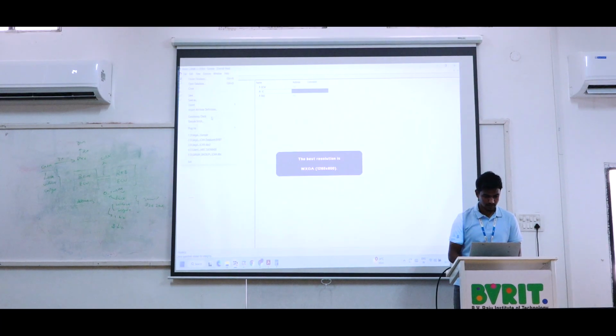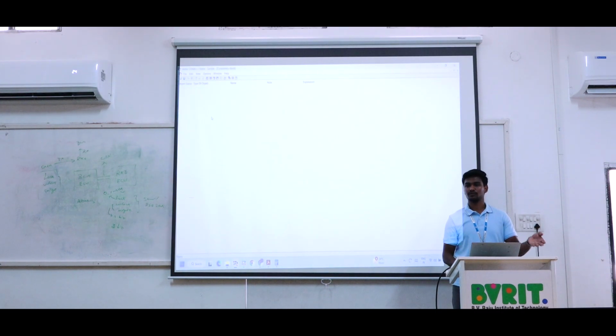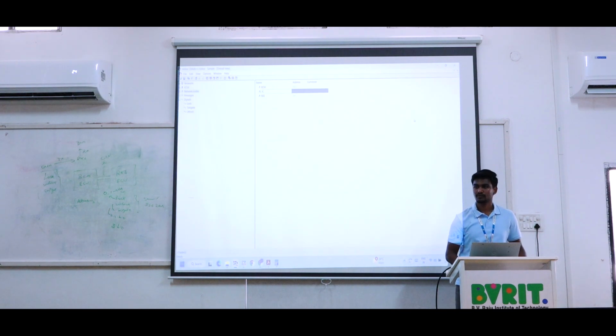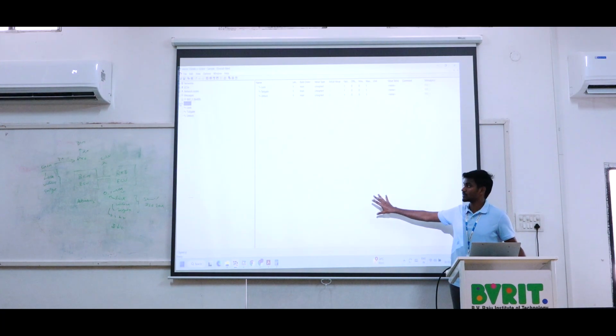So now we can do the consistency check. We have now created a proper database for the different kinds of ECUs with three different signals along with one message. So is it okay? This is the creation of the database. Now it is called a communication matrix. Technically, they call it a communication matrix, not signals, and a database.